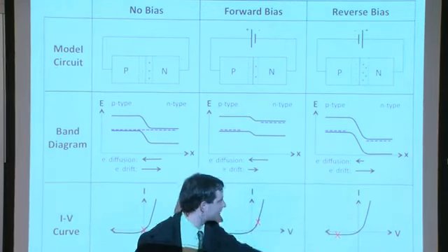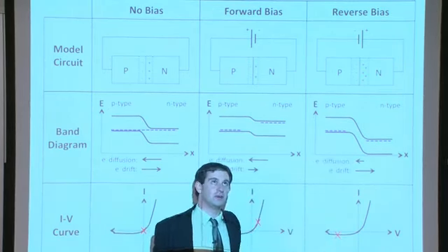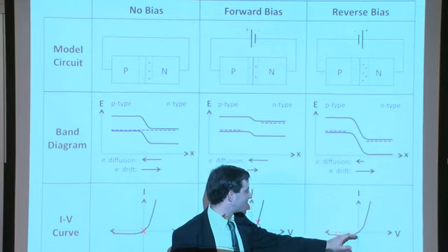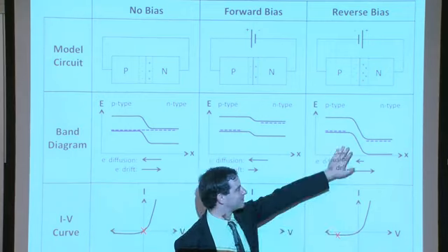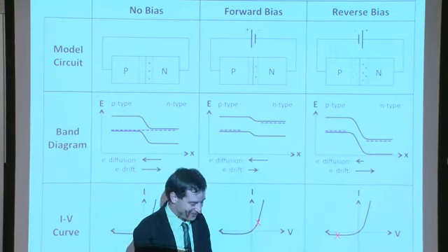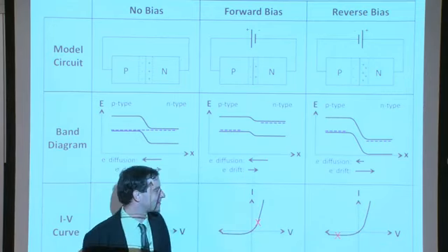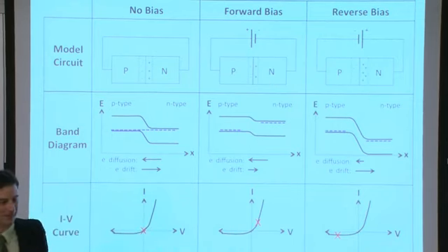So if the solar cell's reverse bias current, or the current at reverse bias voltage, is not low enough, in other words, if the p-n junction is not strong enough, you could have a catastrophic failure of your module by just shading one of your cells. Thankfully, this is one of the tests that are done with the solar simulator to prevent that failure mode.